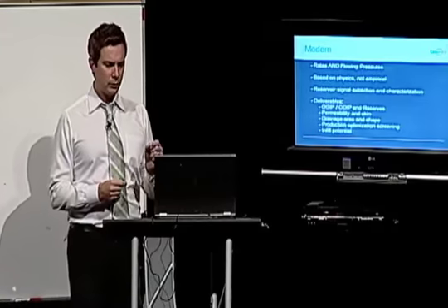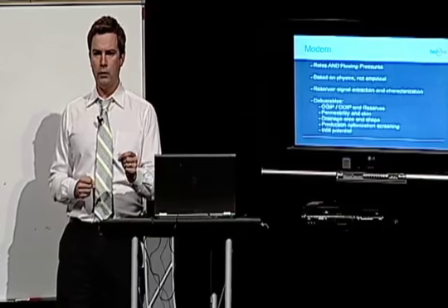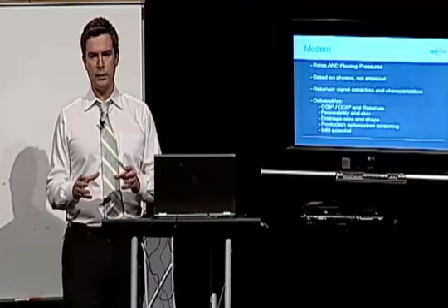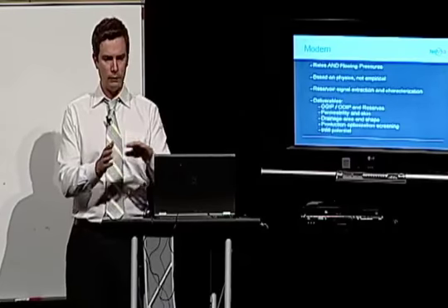The same thing is sort of true for pressure transient analysis, but in pressure transient tests, we usually have a great deal more control over how the data were collected. When we do a pressure transient test, we design the test to follow a certain path. So we control how the rates were, what rate the well was flowing at, what the bottom hole pressure is going to be, how long we shut the well in. And so the quality of the data is often better than production performance data.